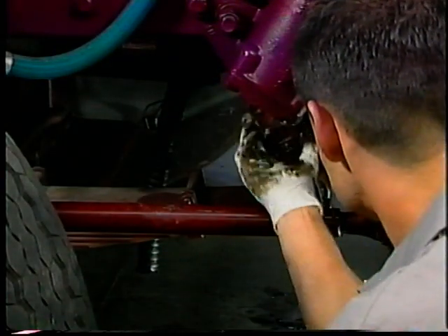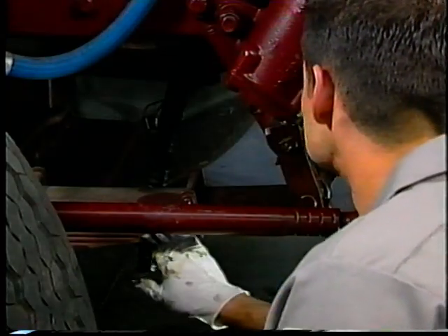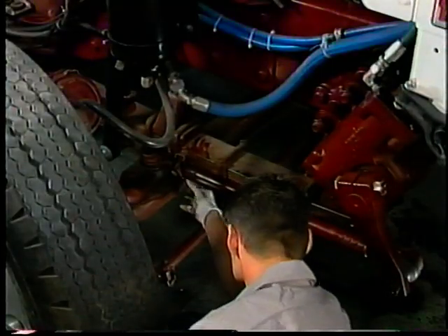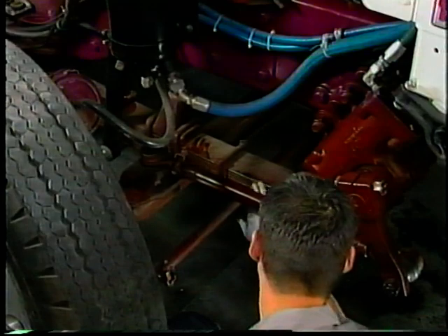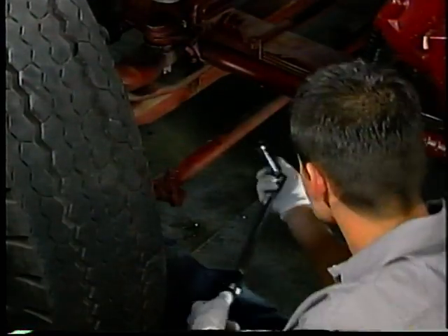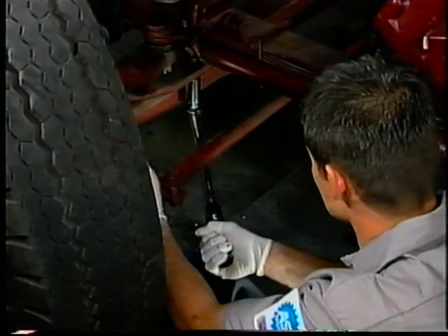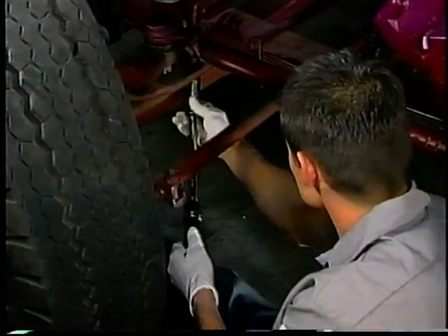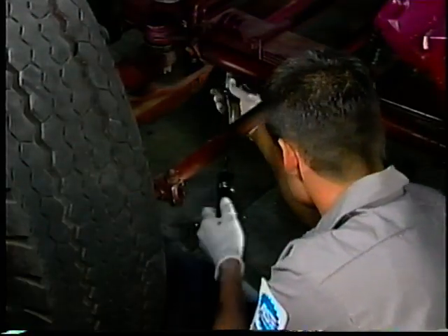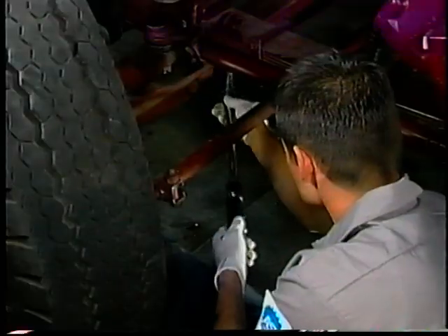Start your diagnosis of suspected spring problems with a visual inspection of the spring leaf, mounts, center pin, bushings, shackles, and U-bolts. If you find a broken leaf spring center bolt, suspect loose front spring U-bolts. A broken center bolt can cause premature tire wear or vehicle dog tracking that can be confused with the type of wear from improper toe-in adjustments.